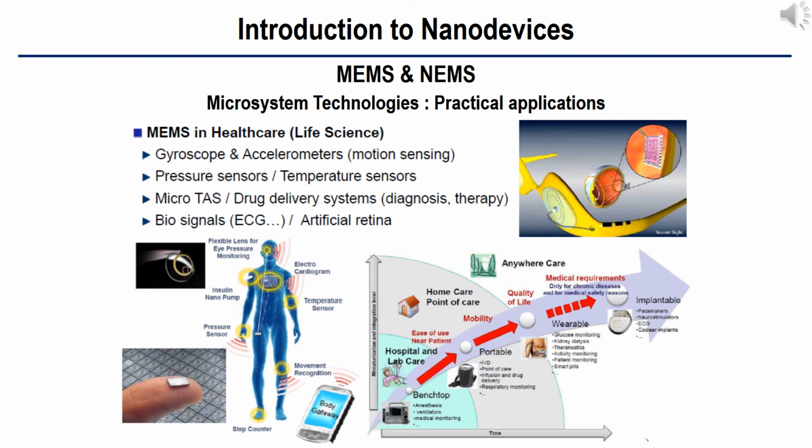There are challenges for NEMS from MEMS. 1. Communicating signals from the nanoscale to the macroscopic world. 2. Understanding and controlling mesoscopic mechanics. 3. Developing methods for reproducible and routine nanofabrication. By overcoming these obstacles, NEMS will achieve some notable advances such as oscillators with resonance sensors for the detection of magnetic forces of a single spin, biomechanical forces, and adsorbed mass at pico or femtograms.